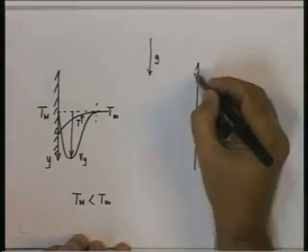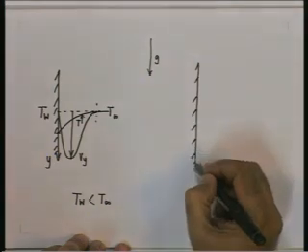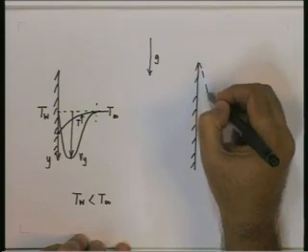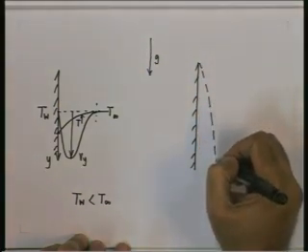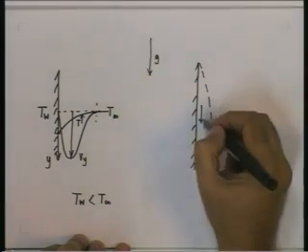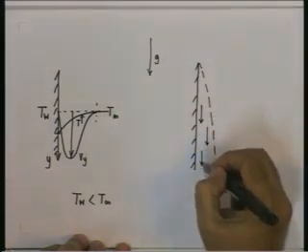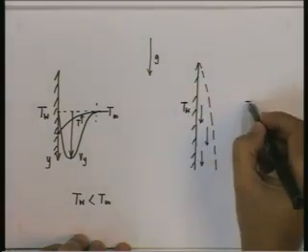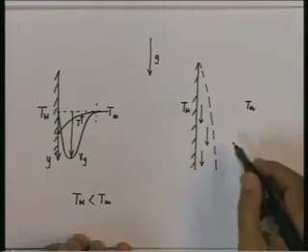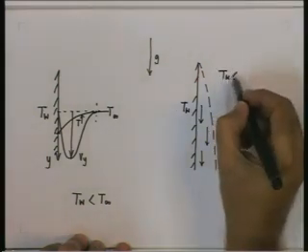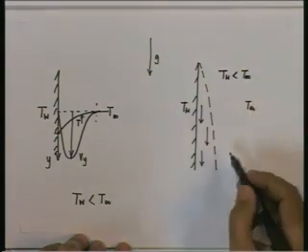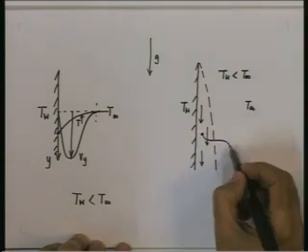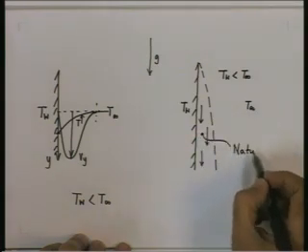The overall view: the boundary layer will now start developing from near the tip, the top edge, grow as you move downwards, and fluid in the boundary layer would start going down. Here also the same situation, wall temperature and free stream temperature. The wall temperature is assumed to be lower than the free stream temperature, and this zone is the natural convection boundary layer.